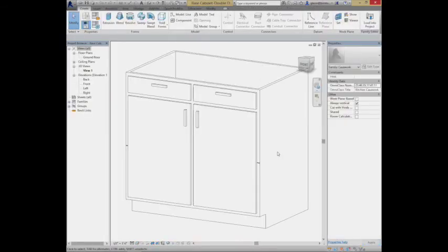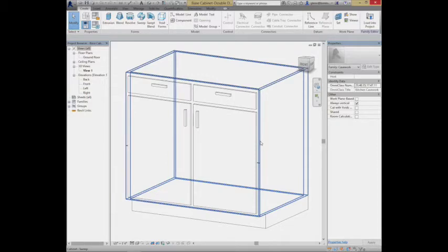So again, what I like to do is often just go through and look at objects and see how they're defined. See if we can debug how those are constructed in terms of where the extrusions are, where the blends are, where the sweeps are. See if we can figure this out. And the way we always do that, either to debug or even to modify it because you want to change the appearance, is as follows. You choose different objects. What I did was I just opened a family as opposed to inserting or loading the object family.